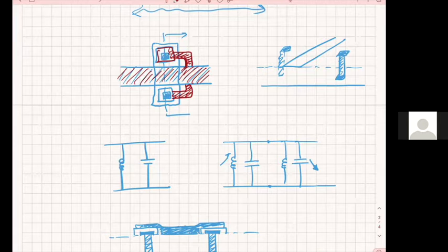So again, what did you learn from all of this that I said? That if your L is very, very low, and it's shunt, and if your C is very, very high and it's shunt, then use them as lumped elements. Just say, I'm gonna create them as lumped elements out of microstrip. There are a lot of different ways of doing lumped elements in microstrip, all right? MIM capacitors and inductors, just short sections of narrow lines.